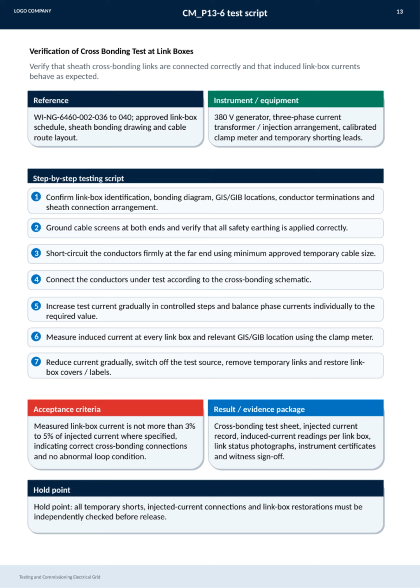All test results are documented thoroughly and include test sheets, injected current records, induced current readings, photographs of link box status, instrument certificates, and witness sign-offs. Finally, there is a hold point where all temporary shorts, test connections, and restorations must be independently checked before releasing the system back to operation.